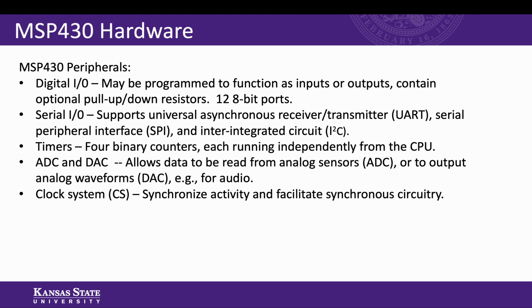The MSP430 has 4 binary timers that run independently from the CPU, so programmatic action can be taken depending on the value of these timers. It also has analog to digital and digital to analog converters to increase its applicability, so it can handle many different scenarios by accepting analog signals and outputting analog signals. Digital too, of course. I mean, it's a digital system, so it has no problem with digital. And it has a clock system which synchronizes activity and facilitates synchronous circuitry.